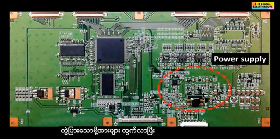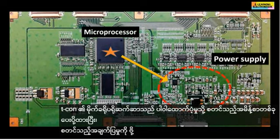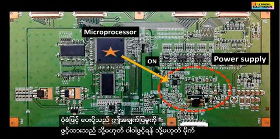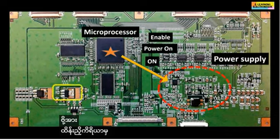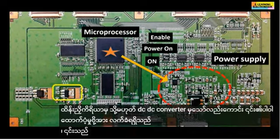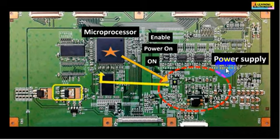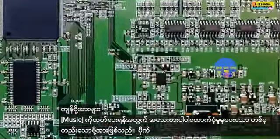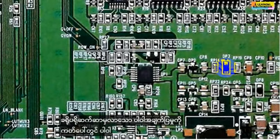After powering up the T-Con, all the voltages of the mini power supply will not be produced instantly. The different voltages will be produced only after the microprocessor of the T-Con has sent a startup command to the power supply. The startup signal is sent in the form of a voltage. This signal is called on, or power on, or enable. The microprocessor receives its power supply voltage either from a voltage regulator or from the DC-DC converter, and this is the only voltage that the mini power supply provides while waiting for the microprocessor to output the rest of the voltages.